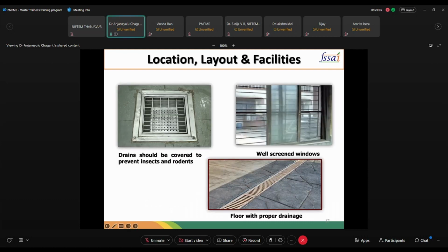See these drainages, they have well-fitted drainages, so they are not just keeping unnecessarily whatever waste is coming in and just going. If you are just putting that, all this material like food wastage goes inside. If you don't have this screening mesh, everything will go into this drain, and finally it gets clogged somewhere. After about 2-3 months, you have to hire a specific maintenance or drainage cleaning person every day. He has to poke that thing, then only you can start the work. Otherwise, there will be very bad foul smells in the premises, and it leads to a lot of problems.